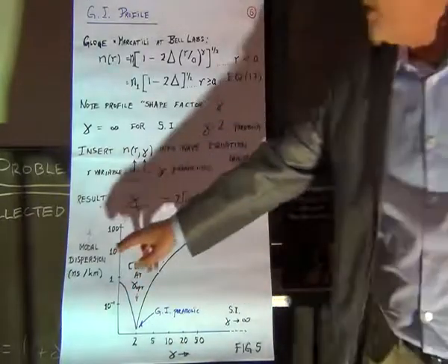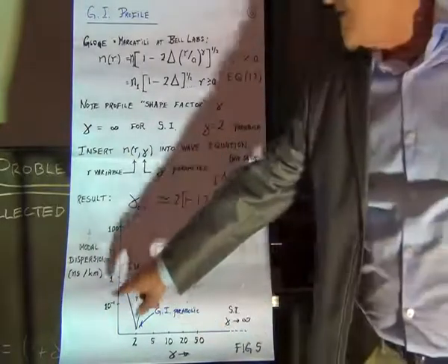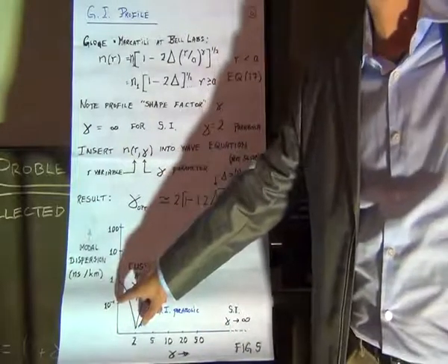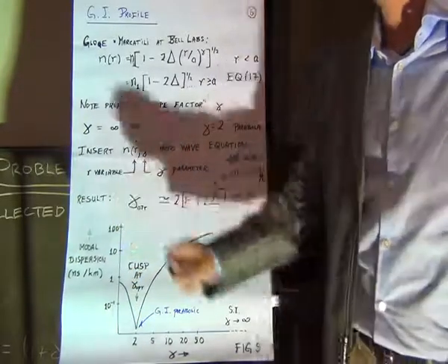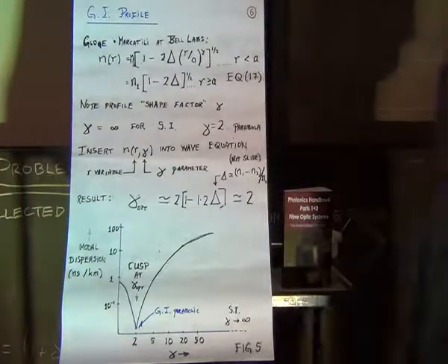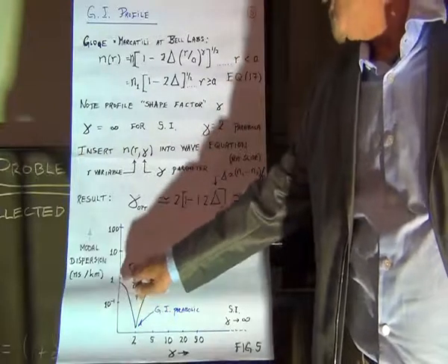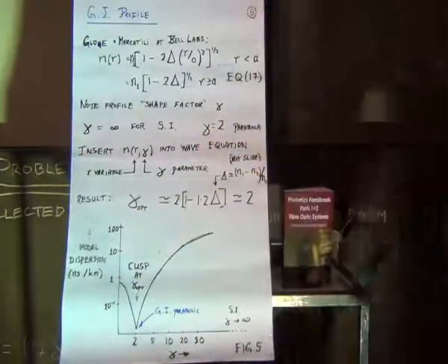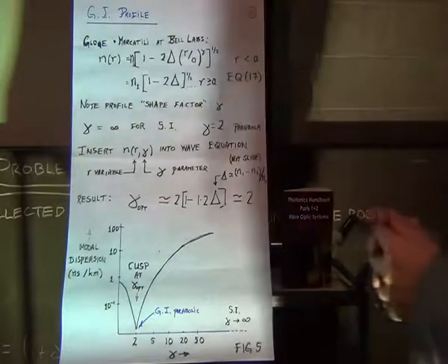And make a note of the axis on the left hand side. That's 1/10 of a nanosecond per kilometre, 1 nanosecond, 10, 100 nanoseconds per kilometre. Our pulse that we inject is spreading out every kilometre by, say, a nanosecond. And if we had our gigabit stream, there'd be total overlap of one pulse and the next one. It'd be useless. However,